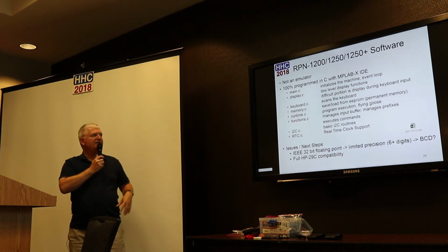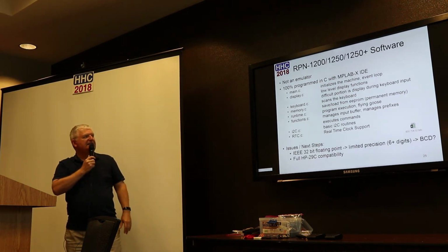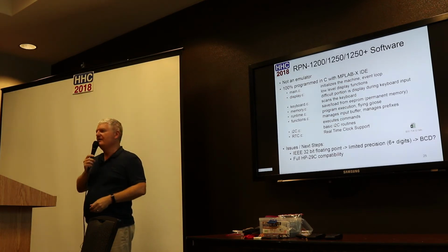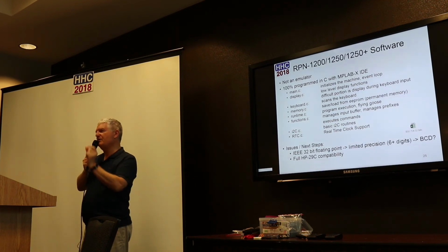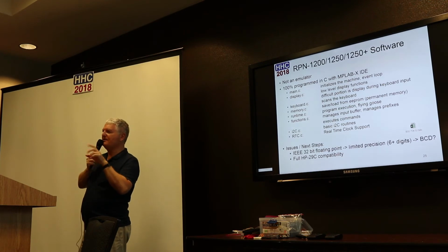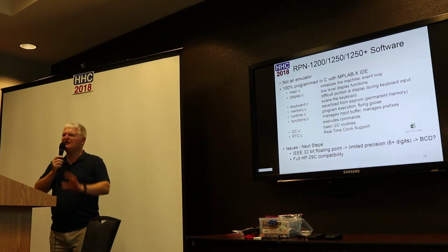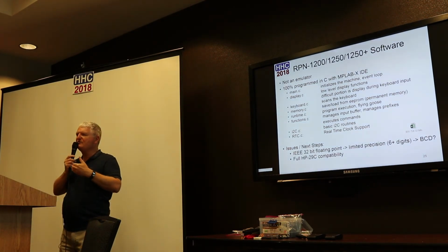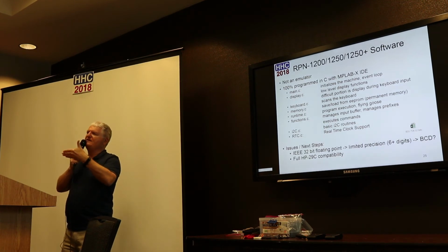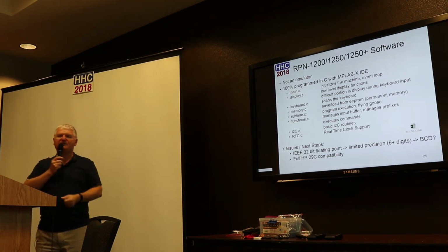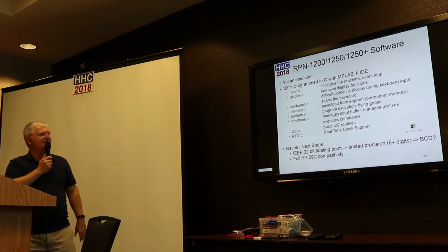Display.c is low-level display functions, and some of the difficult parts here are managing the decimal point, because it's part of a digit, but you type it later, so you have to go back to the previous digit as you input data to add the decimal point, for example. That was the tricky and difficult part, managing the inputs, what you display, and then how that is actually stored as a floating point number to be processed. But yeah, that was fun.